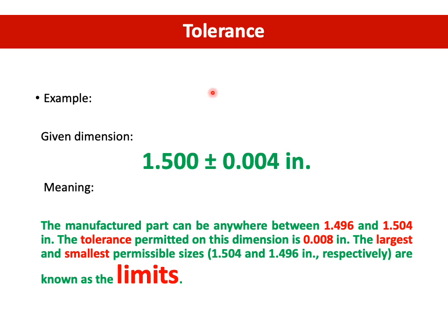So here is the given dimension: 1.500 plus minus 0.004 inches. As you can see, the maximum size is 1.504 and the minimum size is 1.496.